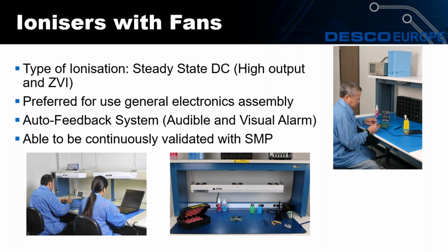It will give you both a visual and audible alarm. If that happens, you need to shut the ionizer down and take remedial action, and that could be cleaning the emitter pins. It could be tweaking it back into balance. There is a trimming pot on there that you can use to bring a number of these ionizers back into balance.